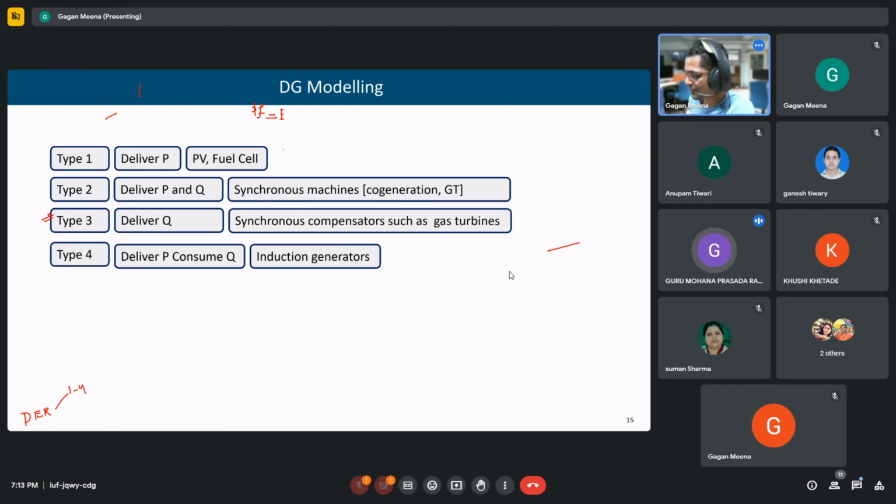Another doubt, sir. The power factor is usually maintained to reduce line losses, but at the place of generation itself we are getting low power factor. Then what is wrong with not having capacitors? So that is why we are not using induction generators. We are using synchronous generators.